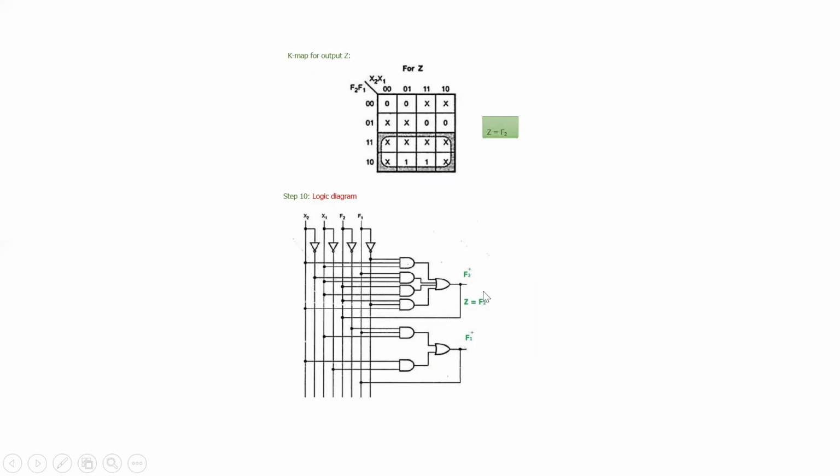So in this design procedure, first we have to draw the state diagram. From this state diagram, we have to write the primitive flow table. From this primitive flow table, we have to derive the implication table for state reduction. Next, we can go for the merger graph to get the maximal compatible pair. Then we can go for the reduced flow table with state assignment.